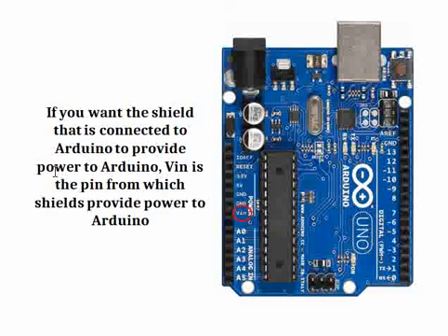And then another important point is, in the same power connector you have VIN. VIN is nothing but a pin to which you can apply voltage to the Arduino. That means 5 volts. So if you connect a shield on top of this Arduino board, you can provide power to the Arduino board from the shield without even connecting the DC jack or the USB. So the Arduino board can be powered by the shields that get mounted on top of it, right?